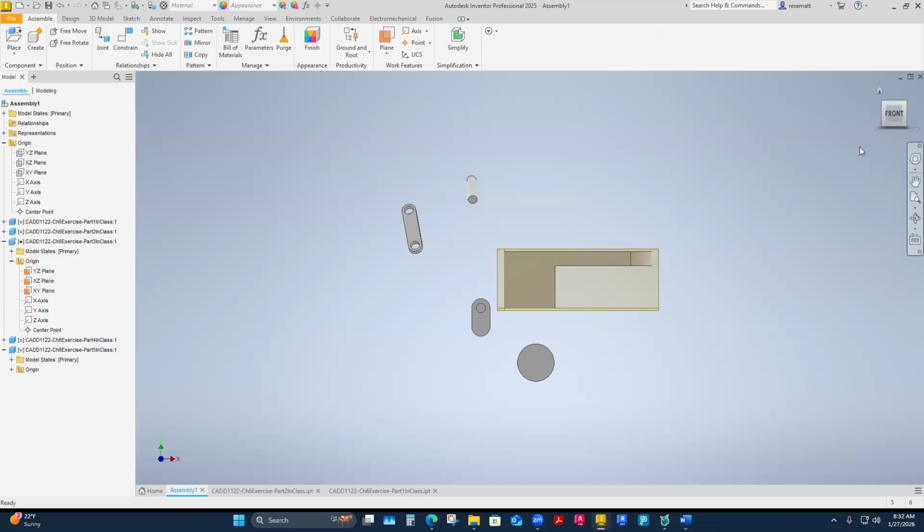But at least I'm not in some skewed angle to the main view cube projection planes. That's important to me as a drafter. Somebody just regular modeling wouldn't care because they're not worried about what it looks like on a drawing. I am, and so I need to know that I'm not in some funky orientation in model space, that I really am grounded and rooted to the origin planes, axes and center point.